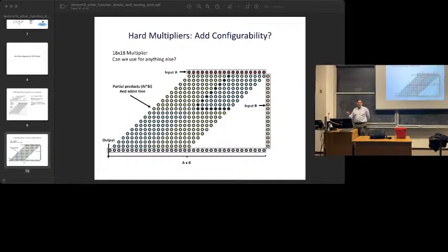So what's really expensive in FPGAs? The routing ports. So how many inputs and outputs does this have? Okay, so before I had 2 18-bit inputs, right? So 36 total inputs. Now I need to have 2 9-bit inputs, so 18, but I have 4 of those. So that's 72 inputs. If I do the analysis for the outputs, it's the same. So I doubled my number of input ports and output ports, and that's not cheap.